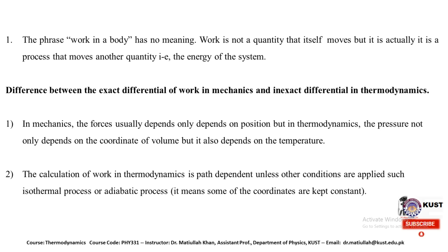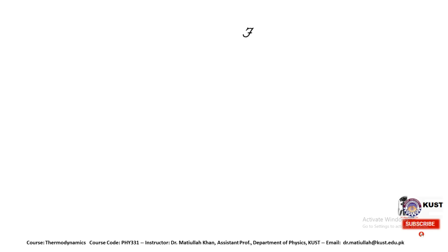So the calculation of work in thermodynamics is path dependent unless other conditions are applied, such as an isothermal process in which temperature is constant, or an adiabatic process in which some other coordinates are kept constant. In that case it is possible, but in the general case it is not possible.